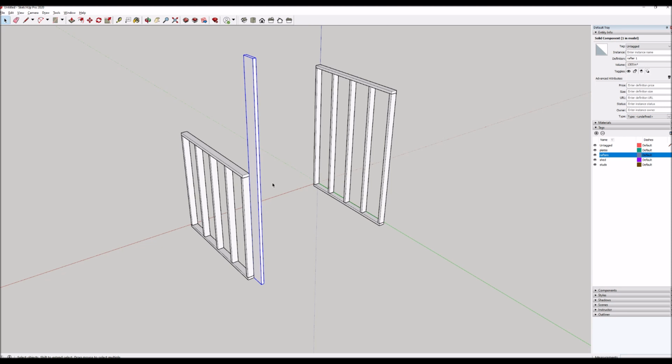Create. Okay. Now, when I'm working with a sloped roof, I like to draw the roof flat first, like I've done here, rather than try to create the geometry in a sloped manner. I like to create the geometry in a simple XYZ flat way and then rotate the entire object. I usually find it easier to do it that way.